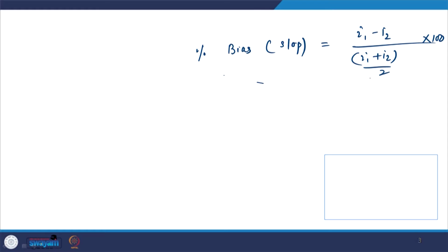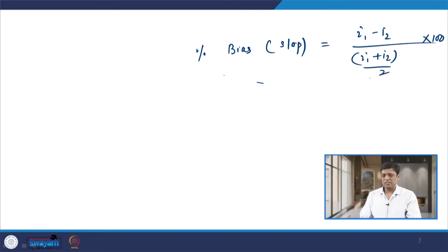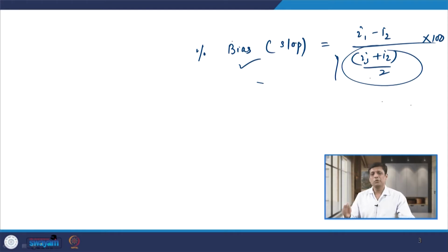You can see that in the case of circulating current differential protection, spill current I1 minus I2 flows because of the two problems we have discussed. In the case of the bias differential relay, even though differential current and spill current are there and this setting is exceeded, the percentage bias setting is not going to exceed. Even though I1 minus I2, the spill current, flows, in the denominator the average restraining current also increases, so the percentage bias reduces.